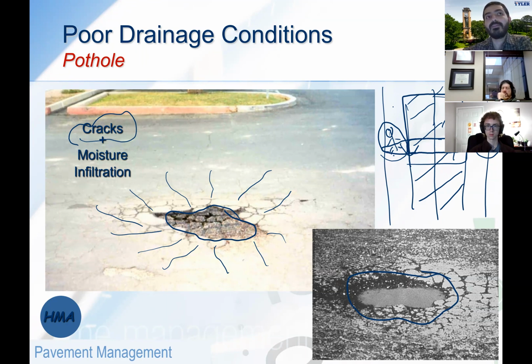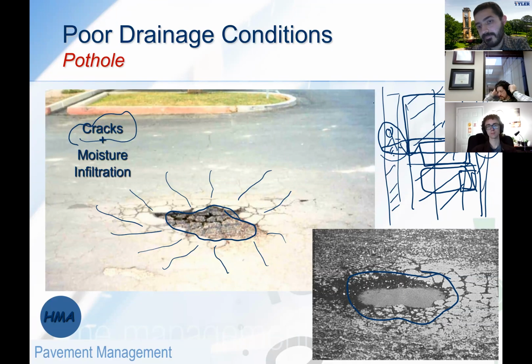Then we have the roller compactors or the pneumatic or rubber compactors. Sometimes drivers get scared and don't want to get closer and closer to the edge. Let's say it's 2 rollers per machine, and they try not to be exactly on the edges. If the driver is not that experienced, things can happen. So what I'm trying to say is if the edges are not getting enough compaction, they're going to end up with higher air voids compared to the middle part of the structure.